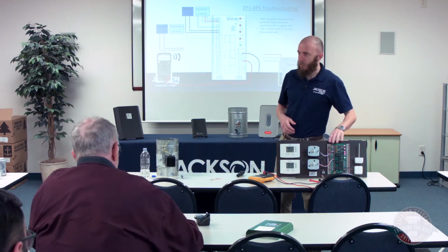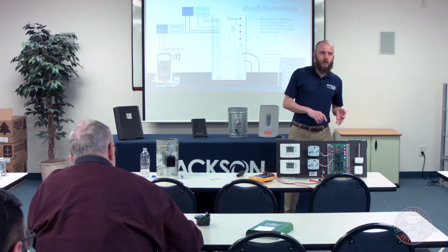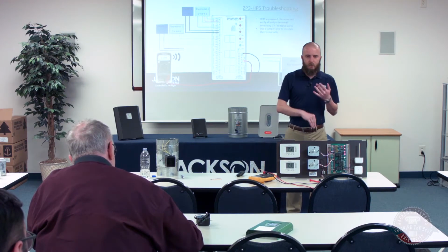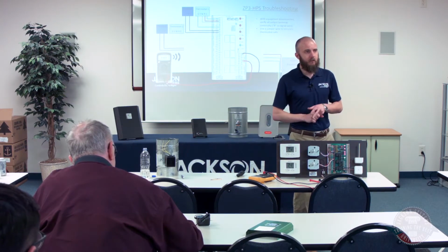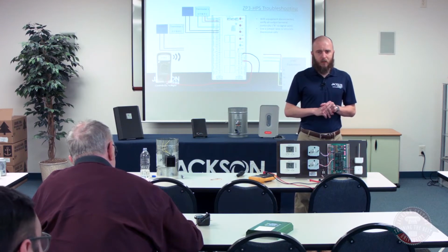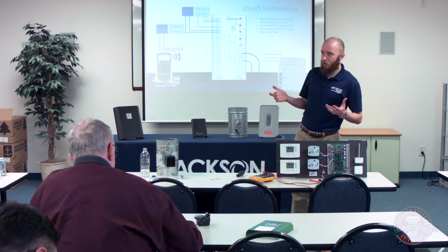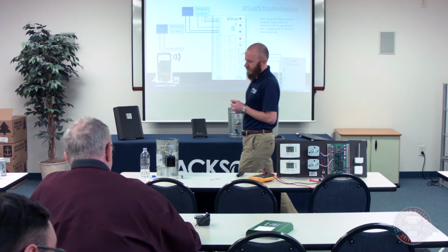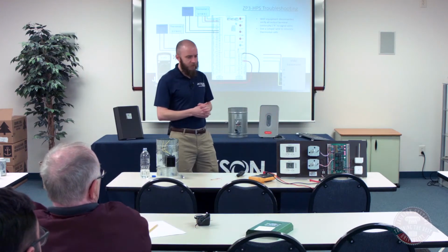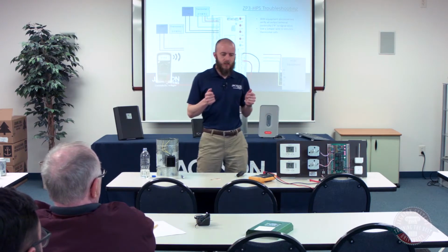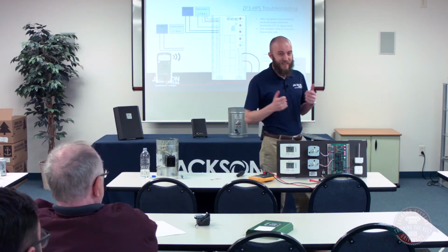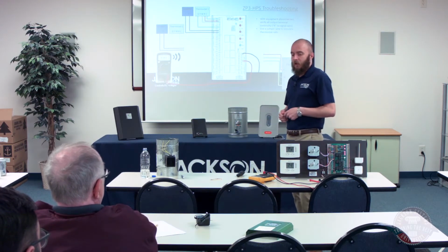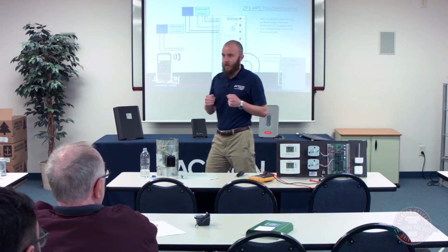So on the heat pump panels, there are outdoor temperature sensors, and heat pump and heat cool panels will typically have discharge air sensors. In a lot of cases, those are standard 10K ohm sensors or 10K thermistors. So you can check those with the resistance setting on your multimeter. So disconnect them from the panel to do that, but you can check the resistance there and see if it falls within range.